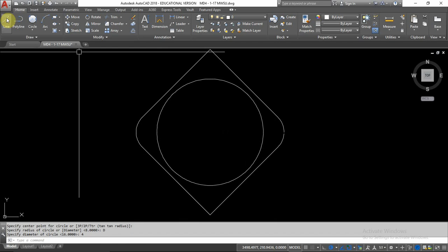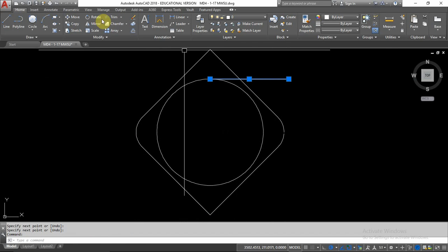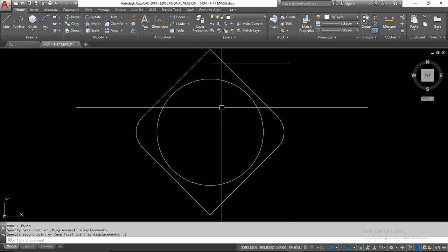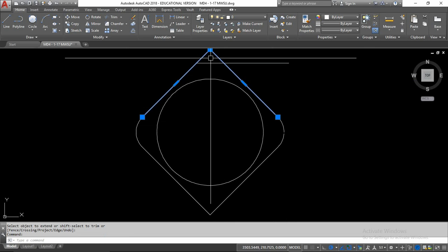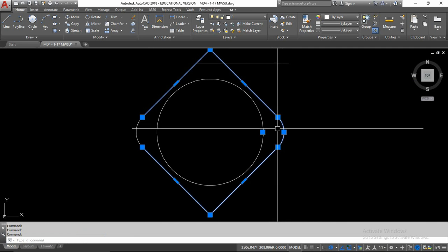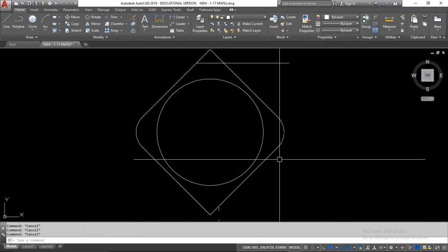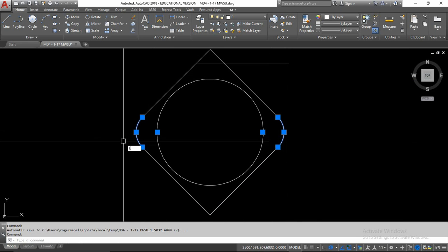And then I simply draw a line from here over, and then either copy or move this up a distance of 0.6, and then extend. I just right click for anything and move it there. Now this is a polyline. And then I had fillets added to it. This would have kept it all as a polyline if I had the trim mode. Here, let me show you what I mean by that real quick.